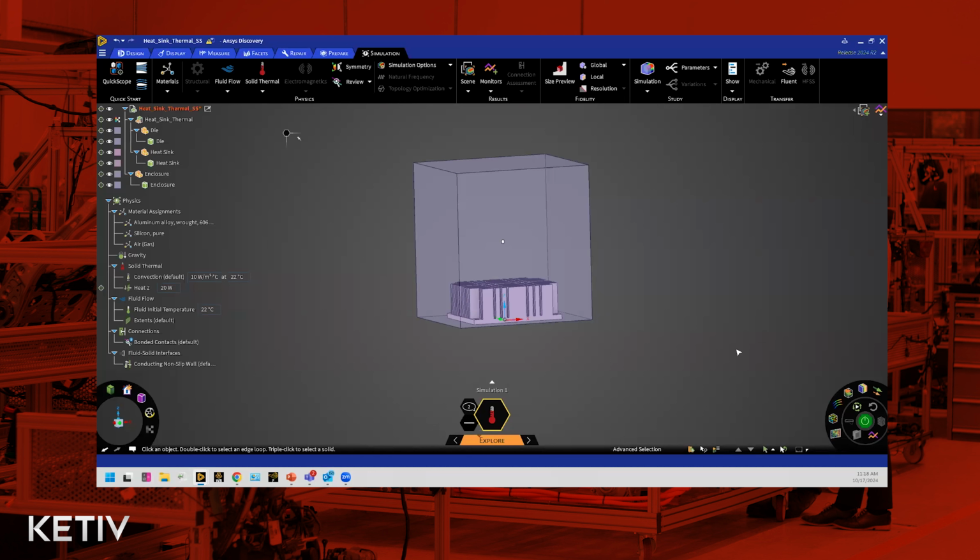So in this particular case, we are going to assign pressure boundary conditions everywhere. And that way, whatever movement we see in this domain is purely because of density variations or purely because of buoyancy. So let's go ahead and do that.